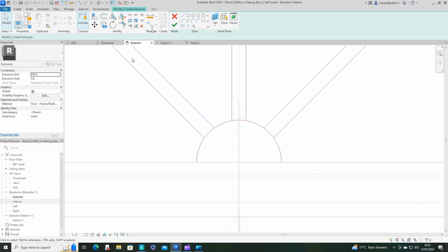Okay, so slight issues we've got by here at the moment. We need to make sure that is a closed loop there. And then this, we're just going to drag that round to there and join that onto that. And then we're going to do a few more of those circles. So the center, start, end, and another one, and one more.